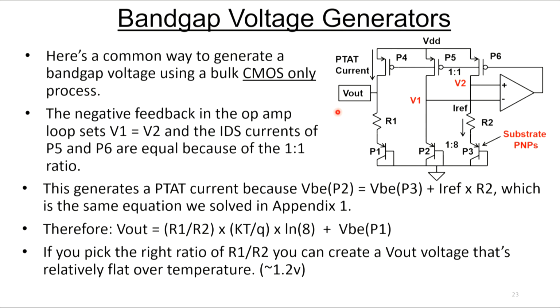Okay, so let's talk about bandgap voltage generators. Here's a way to generate one using a bulk CMOS process. So all you have here is CMOS devices. You have a bunch of PMOS devices on top. You've built an op amp.